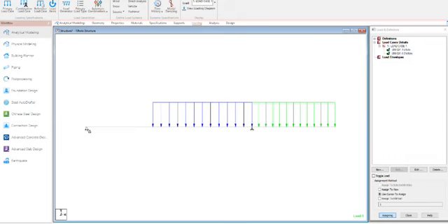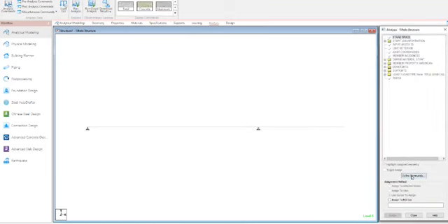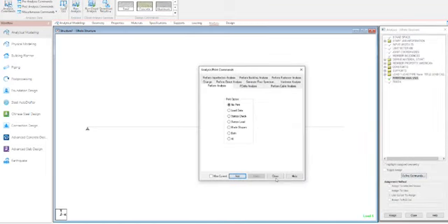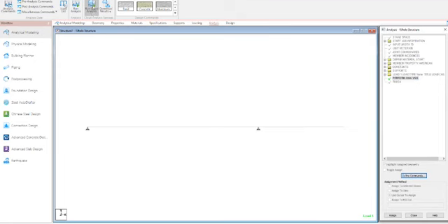So here what we are doing, this is 5 meter span. Out of that 5 meter, 3 meter span we applied 1 kilonewton, another 2.5 meter we applied in uniform distributed load. Now we will see like here the reaction should be upward. Then it will have the sagging bending moment here. Then this will be like this it will come. Okay. So let's go to the analysis and perform analysis, and we will run the analysis.